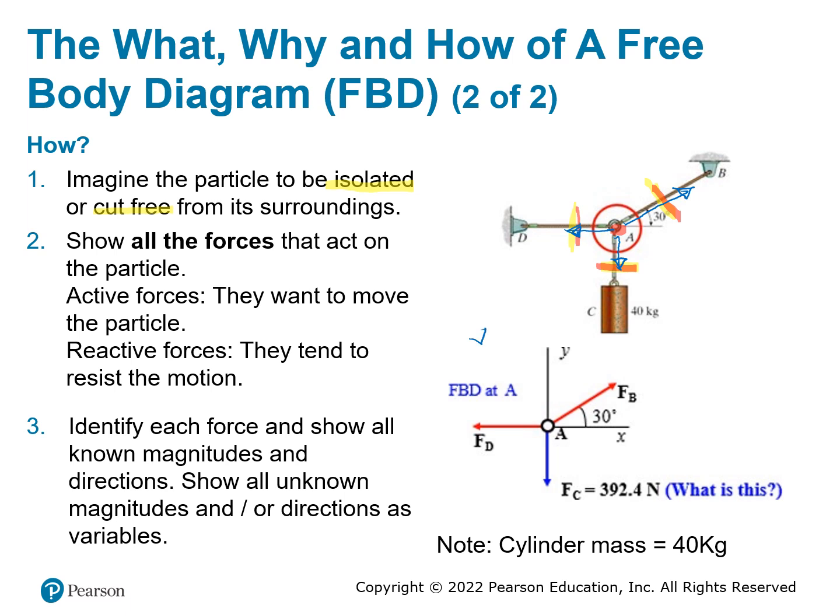You're going to have three forces, and that is what we draw here. Point A is the point that you are interested in. You cut off these three cables, and they are tension forces, and you mark each one of the forces with a different subscript. Sometimes people like to write F of AB, which represents the force along A and B, or you just simply write this as the force of B, which is the point it is connected to.